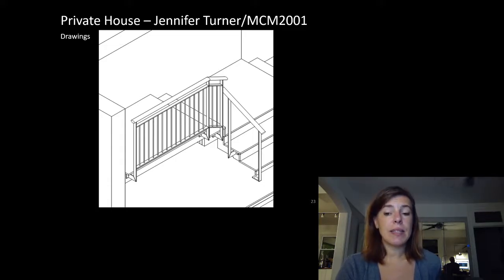It has the same stiffness though, so often you end up with a stiffer guard because you need more material. So the perception is that a stainless steel guard is nice and stiff, but it's because we need more material because it's less strong.